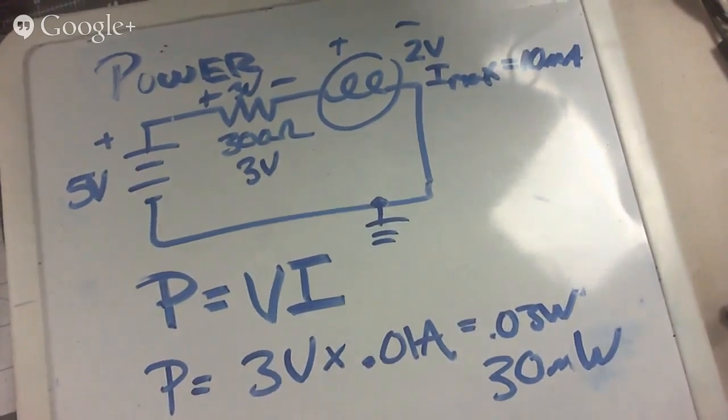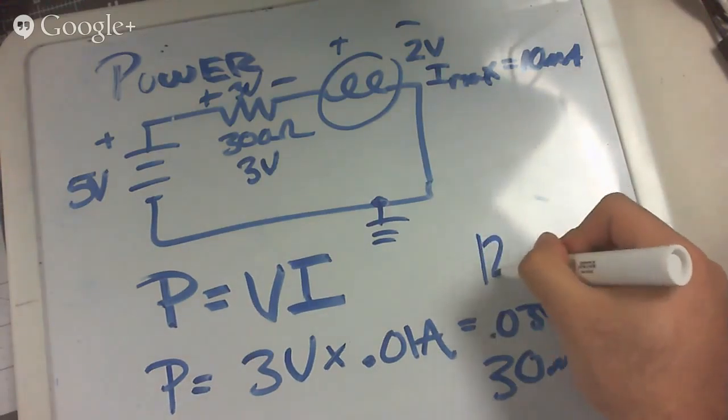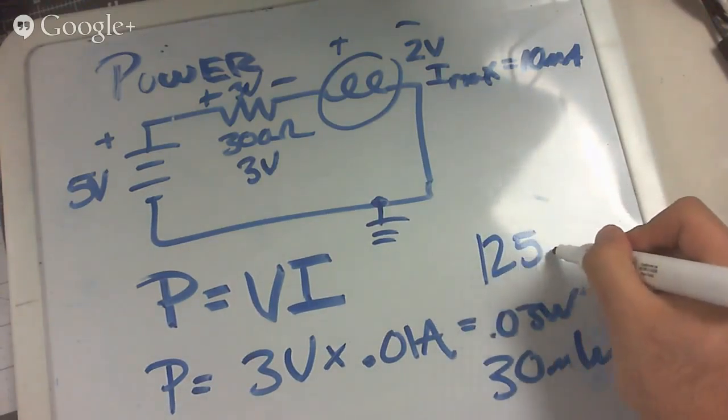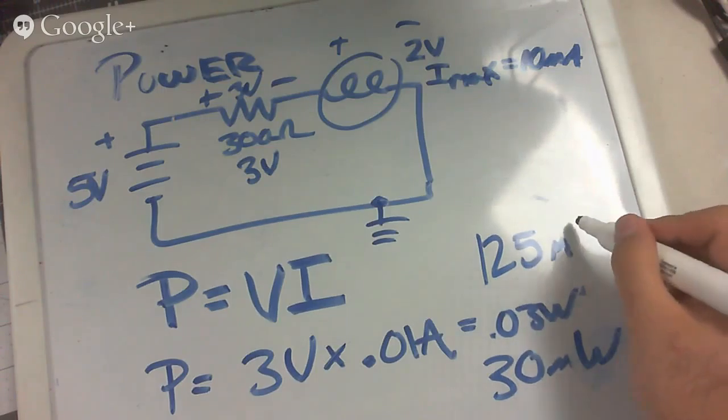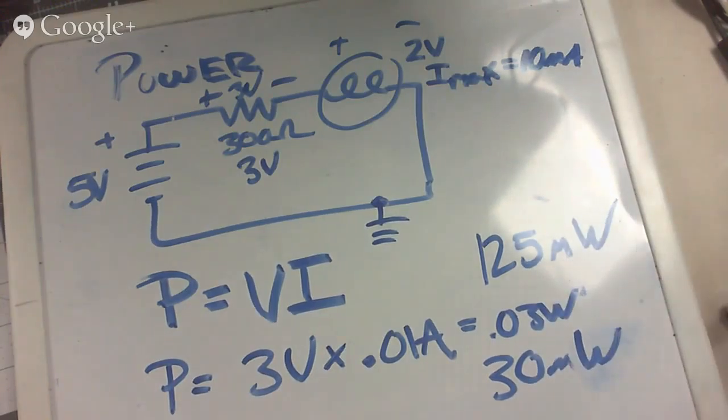They'll all dissipate it. It's just whether or not they're intended to be built that way. Reality is, yes. So their resistor values, you'll see there's 1/8-watt resistors, quarter-watt resistors. 1/8 of a watt is 125 milliwatts. So I could go out, and my 30 milliwatts is way under.